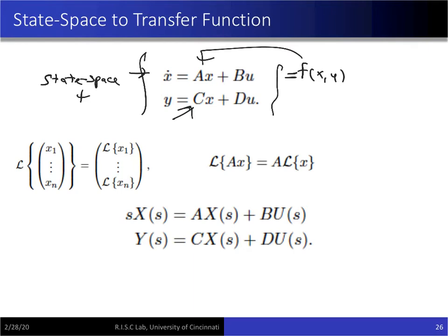So things are simple. Here also we can apply Laplace on both sides of both equations and basically solve for y and the ratio of u. This is where you can also show that if your initial conditions are not 0, your output will be a combination of the response because of initial conditions and because of the input. Separate it out, basically. So the idea is, take Laplace on both sides of this equation.